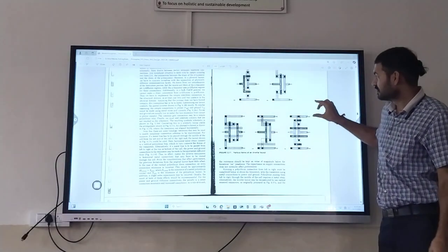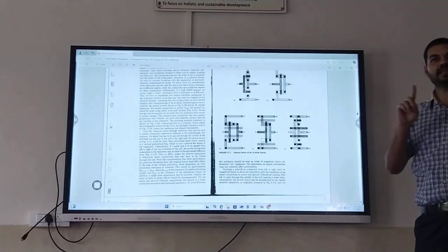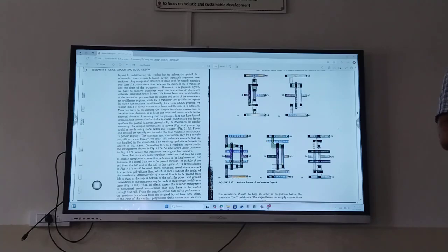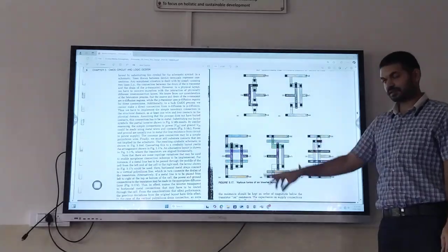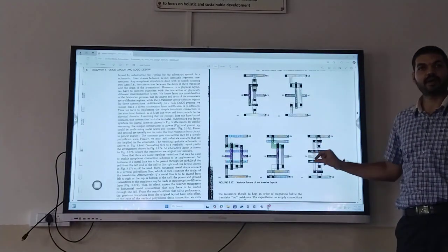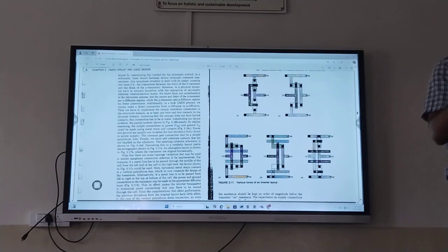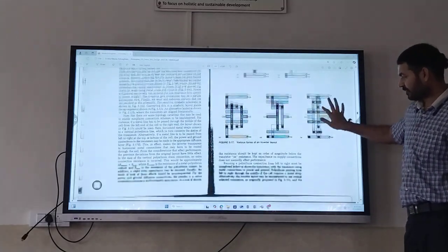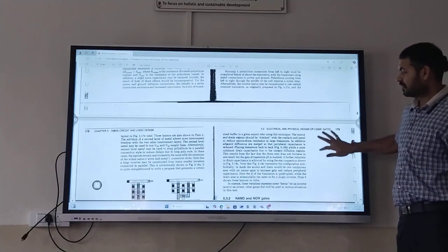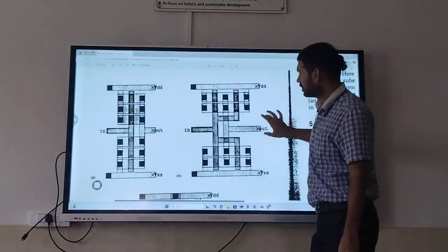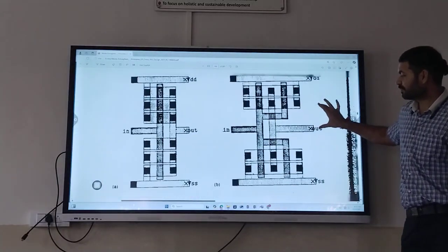So I have shown you different forms of the layouts. Okay, all these layouts are of inverter only, but as I said, we should be very flexible in drawing the layouts depending on the conditions, which all signals or which all layers are passing through it, or how efficiently we can draw the layout of the circuit. In the same way, we have different layouts. Here what we have is, this is again inverter, but it is parallel inverter.